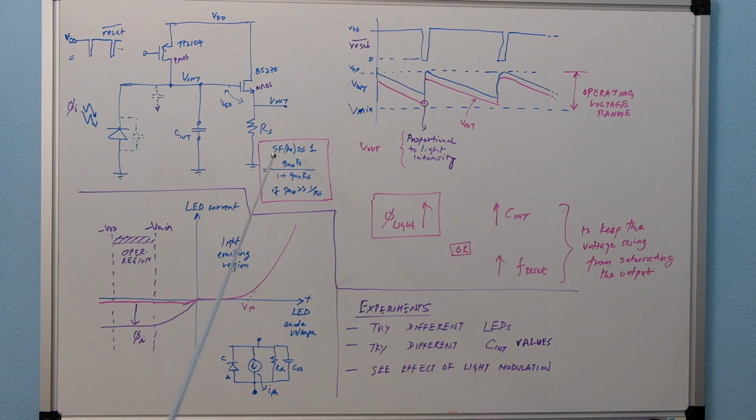So in this particular example, we have the GM of this transistor, and the data sheet gave it to be around 320 millisiemens at 400 milliamps, or 200 milliamps, I'm sorry, and the current in this actual circuit is 1 milliamp.